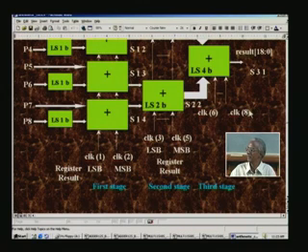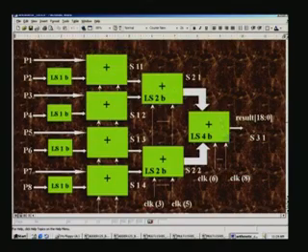There are internally pipeline registers here, and there are basically 3 stages of addition, and also there is a shift happening inside here. And in Verilog shifting is very easy, we have only to take the relevant bits, and therefore the whole multiplier is reduced to mere addition, nothing more, because even the 2's complement sign is taken care of by mere addition, and so the algorithm turns out to be very straightforward and simple.